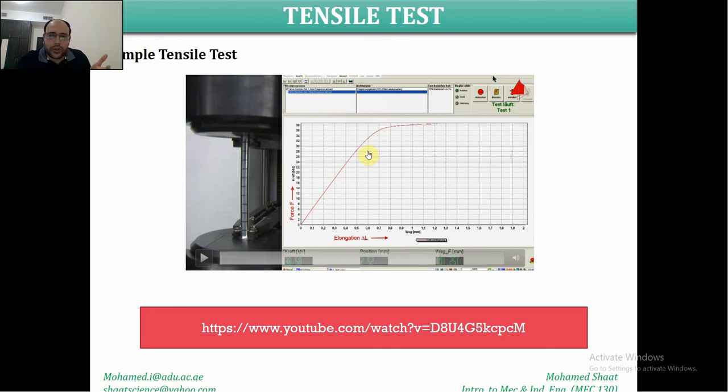We end up with a smooth curve, a transition from the elastic region, the linear relation, to another non-linear relation. We obtain a smooth transition from the elastic to the plastic region, but there is no specific point that we can say is the yield point of this material. Make sense?